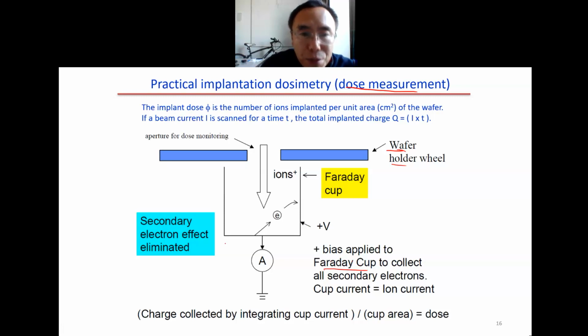So in this case, this may be the size here, maybe 5 millimeter, very, very small. We have a small opening here. So then we have the ion come here. There may be some secondary electrons. But here we have these positive barriers, so the electrons will be trapped to the side wall. So in the end, there will be no charge. All the charges will be collected by this cap. No ions or no electrons can exit. So all the charge will be collected.